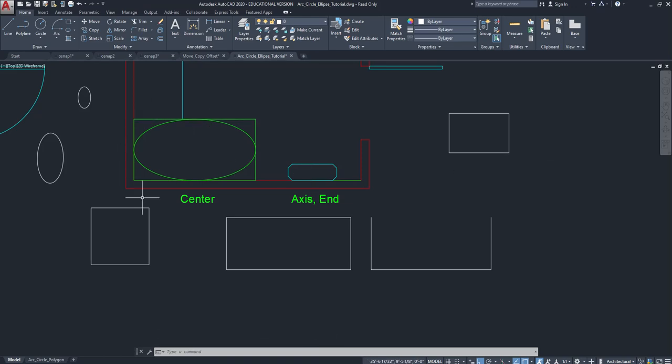I'm going to measure this bathtub and then I'm going to show you how to create a dimensional rectangle, okay? DIST, distance, enter. I'm going to click, that is 2'6", and I'm going to hit enter to reinitiate that distance command without going up to the icon. Click. By 5 foot. So 5 foot by, was that 2'6"? 2'6" by 5 foot. Okay.